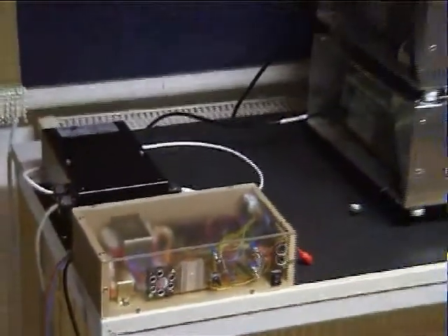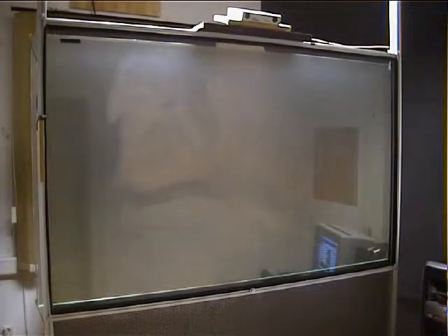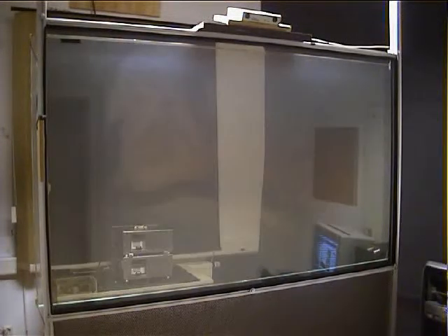While 2 display projectors generate the stereoscopic images of the augmented graphical content, an illumination projector reconstructs the hologram as explained before. All 3 projectors are synchronized with the shuttered projection screen. This allows a reconstruction of the hologram only when the screen is in the transparent mode, and an augmentation only when it is in the diffuse mode. The left and right stereo images of the graphical scene are displayed with twice the frequency of the screen's shutter frequency. This is 100 Hz and 50 Hz respectively in our case.